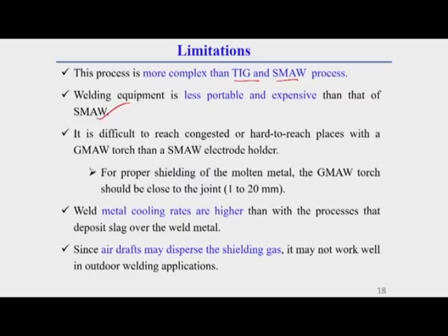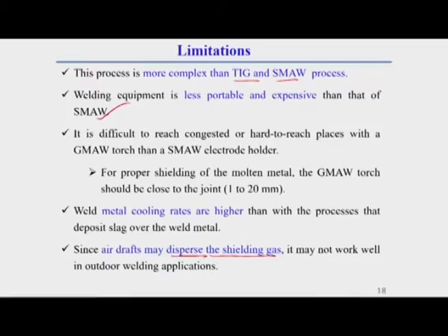Generally the weld metal cooling rate here is higher than in the SMAW welding process. So the weld we get here is less ductile compared to SMAW. Another thing is that air draft may disperse the shielding gas. Due to the air draft there is a chance the shielding gas will move or disperse, so it may not work well in outdoor welding applications where there is a continuous flow of air. This welding process is not suitable there.